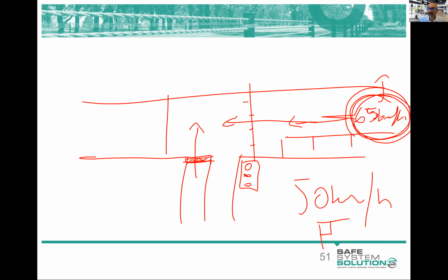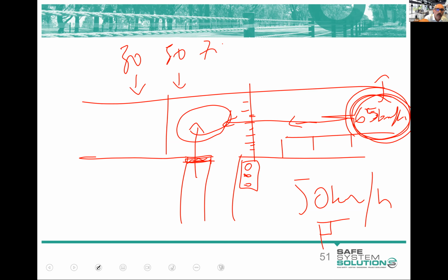Yeah, so Alex has put in a good point there. A primary is defined as elimination of a crash type at a specific severity. And that's right, we can still have the crash type available. It's just that we've ensured that the energy of that crash type is within tolerable levels: 30 or below where pedestrians can crash, 50 or below for side impact, 70 or below for head on, and those all come from module 1.